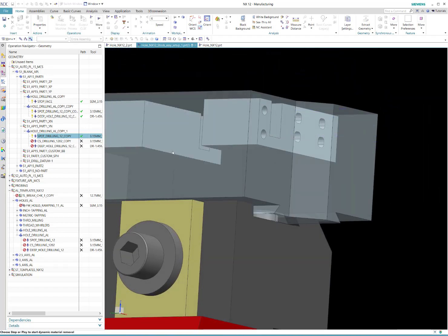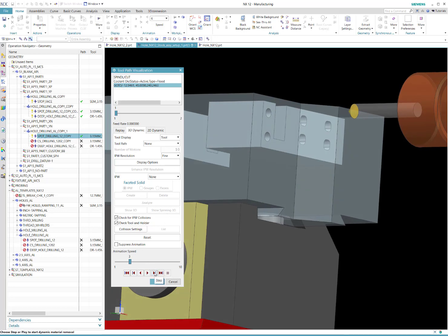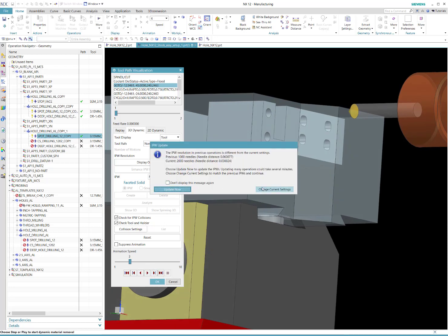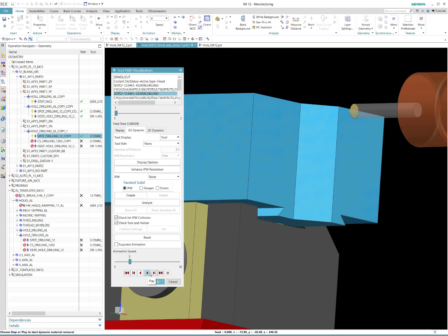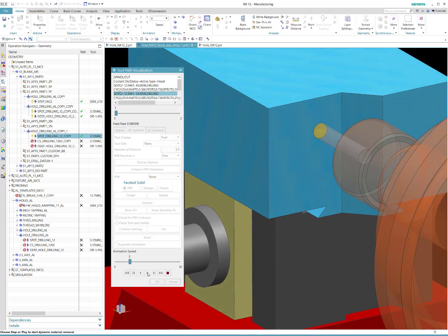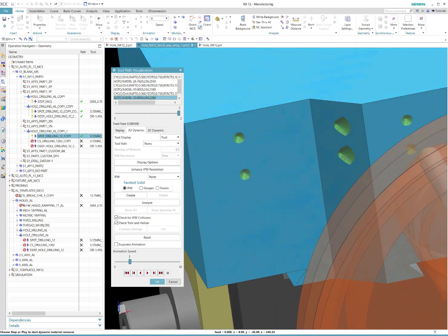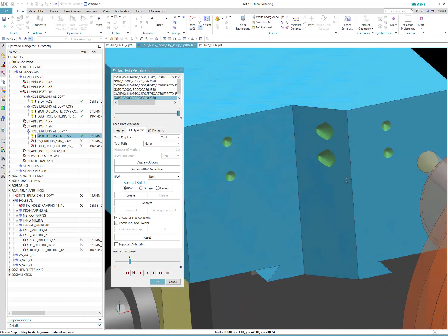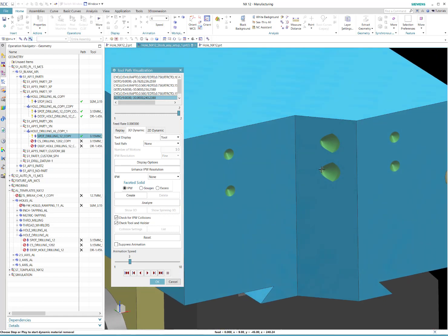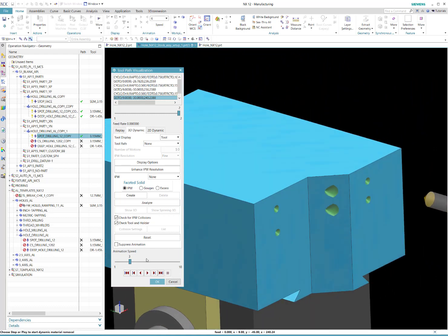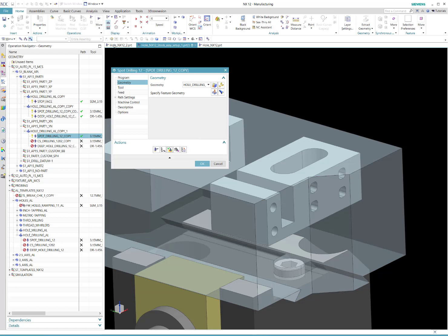Of course, if I play that through, I mean, that's what you get when you don't mill a little flat, but still that'll work, especially in soft material. And as long as that center is breaking through, my drill should be okay. It should pick that up and work with it. I kind of like putting the flat in, but for this demonstration, since I did it on the other side, there's no reason to repeat it.